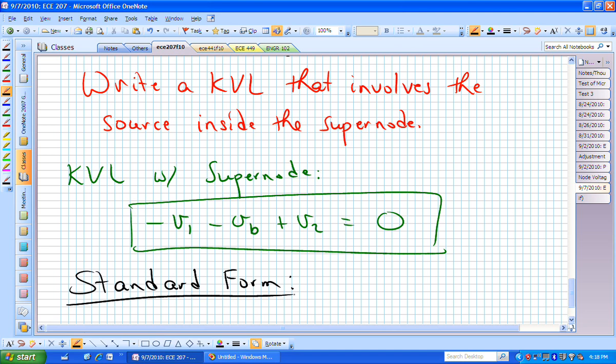And we can relate that to these node voltages that we've defined. One way to do that, in this problem, is to use KVL around that inner loop in our 3-mesh circuit. That allows us to identify one more equation that involves V sub B and the two node voltages, V1 and V2. Is everybody okay with the correctness of that equation?